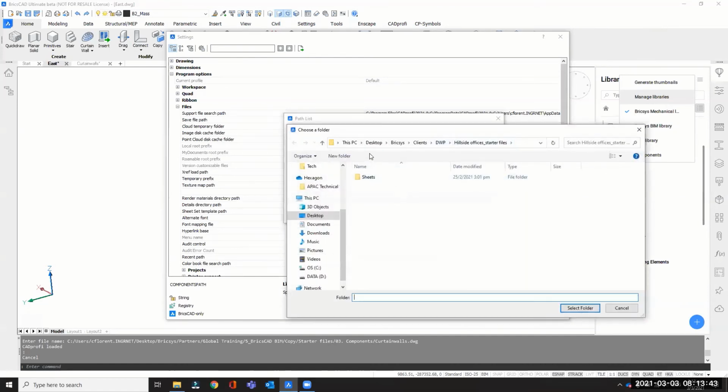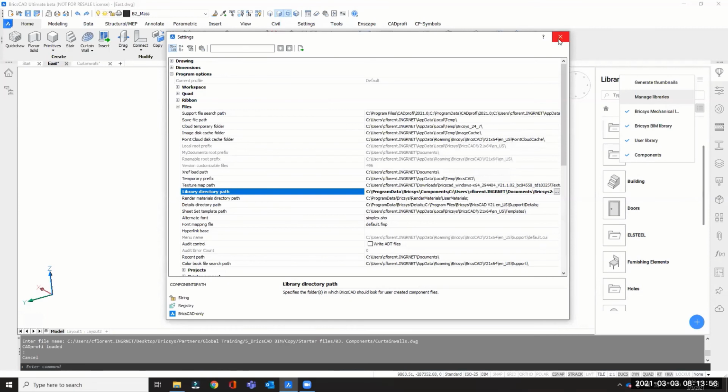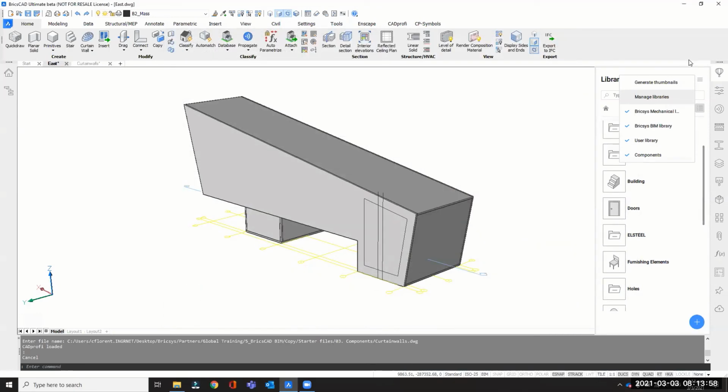And you should be able to find and go through your machine where that specific library folder might be for your RFA folders. So you can select a folder, click OK, and that should be added into the library that you have for the components panel. So that's just a tip for you when customers ask about this, because we do get asked about this a lot.